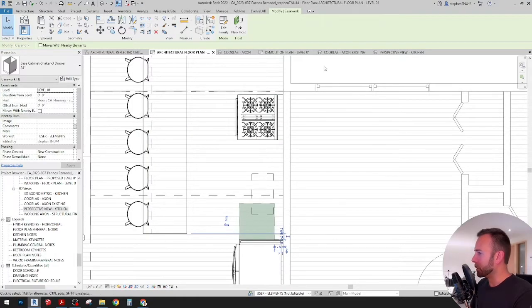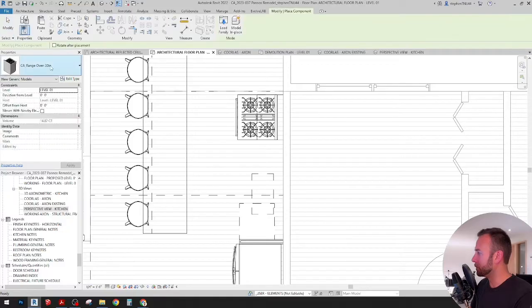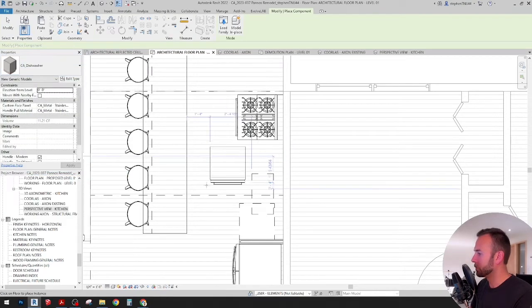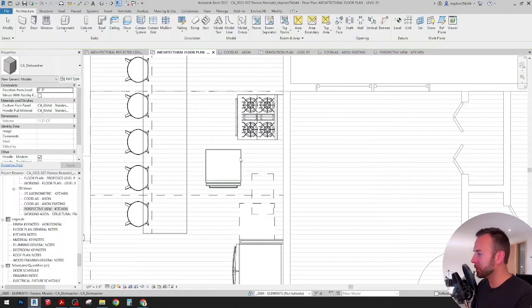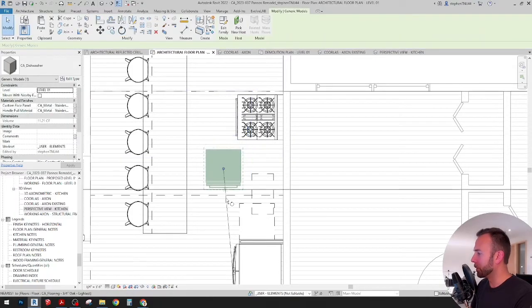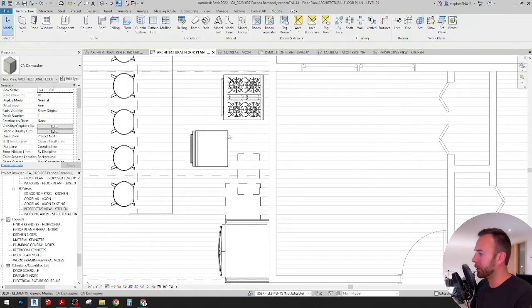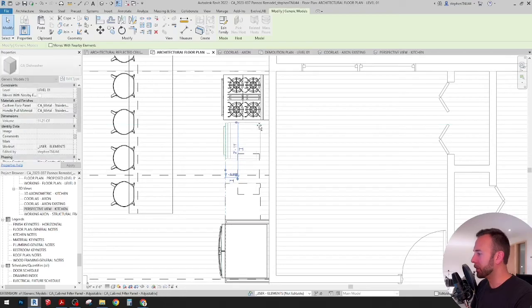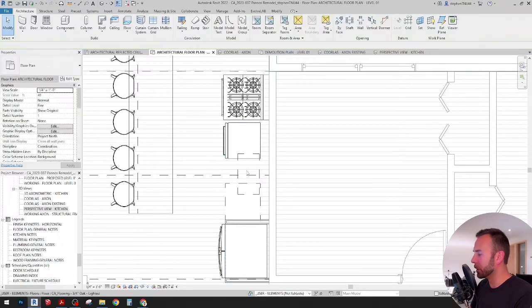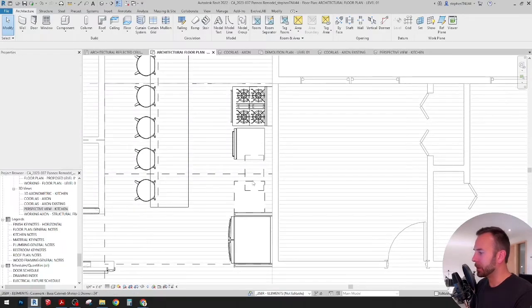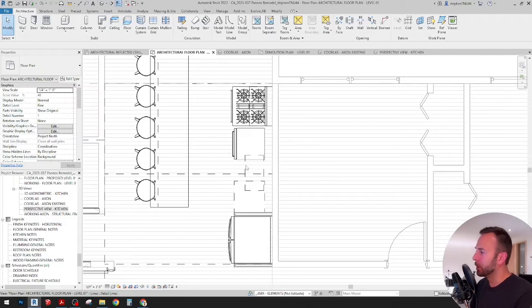We're gonna have to fit a dishwasher in here, so let's toss that in. Again, that's a standard dimension, 24 inch width for that. And that typically goes adjacent to the sink. So you can see we're starting to get squeezed in there. And sink cabinets are typically either 30, 33, or 36 inches.